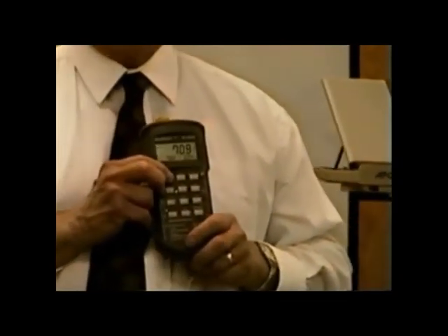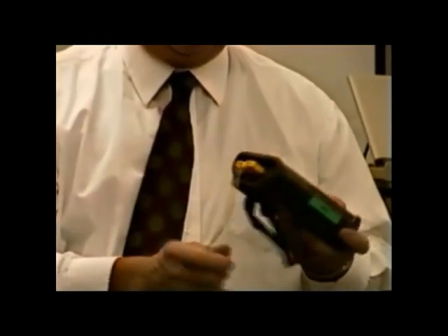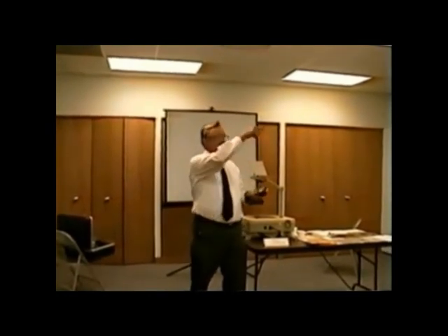I'm going to come over here and get a thermometer, because this is a nice tool to have. We would suggest that you do get a thermometer. I don't know if you can see that, but that's okay if you can't. It's got a digital readout, and this is what makes us good at what we do. We can use pocket thermometers with a digital readout, and it works terrific for heating because we can poke a hole in the return and stick the thermometer in there, or poke a hole in the supply and stick it there. But you can't use the pocket thermometer when we check superheat and subcooling on air conditioning. That's the reason we would suggest that you get one of these thermometers.